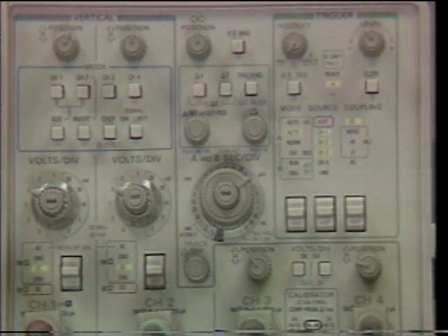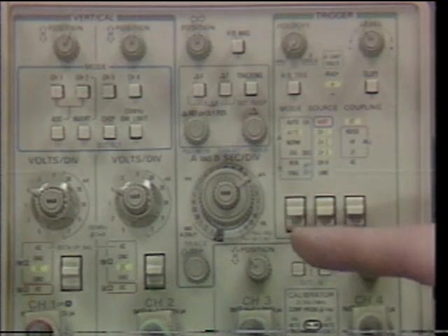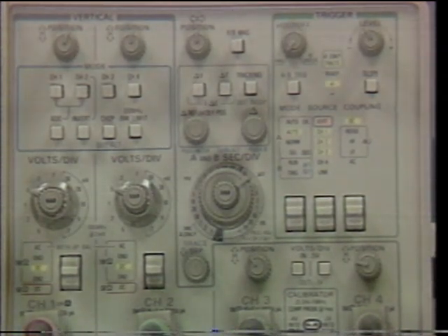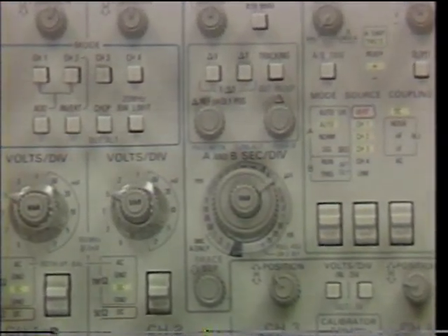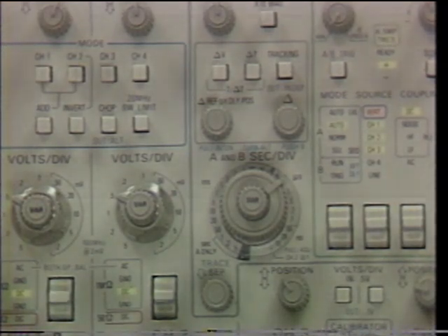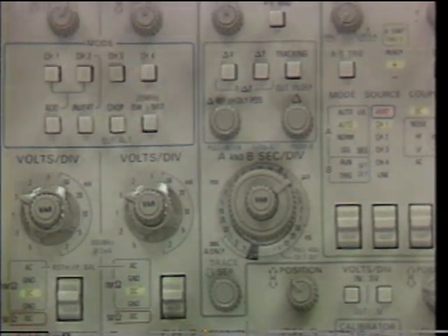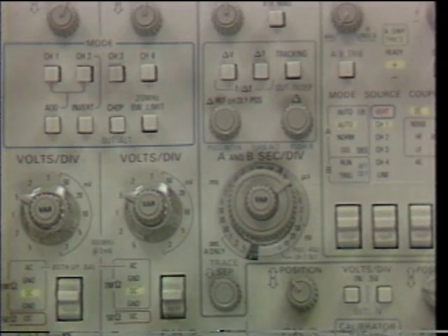Now, while the vertical source is selected, we have really two modes of operation. When the mode is either auto or normal, and also including single sequence, the vertical source produces a composite trigger. That is, each of the selected channels in turn provides a trigger, provided the vertical mode selection includes the alternate switching mode rather than chop. If we select chop instead of alternate, the source selection is automatically the lowest numbered of the displayed channels, so that the scope does not trigger on the switching waveform, rather it triggers on a valid signal waveform.